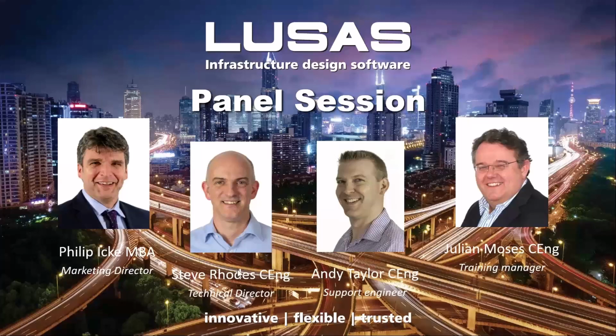And I think the final one is Steve's. Yeah, likewise, really. For the FCM wizard, you can run that from any bridge license, and you're running the wizard, so you can enter all your data, and that's obviously a substantial little job if you're designing one of those bridges. But you won't be able to build a full nonlinear and transient, i.e., a creep analysis model, without owning the nonlinear and transient license. So you could have someone working on that wizard and then passing it over to a colleague who has the nonlinear license, if that makes sense.